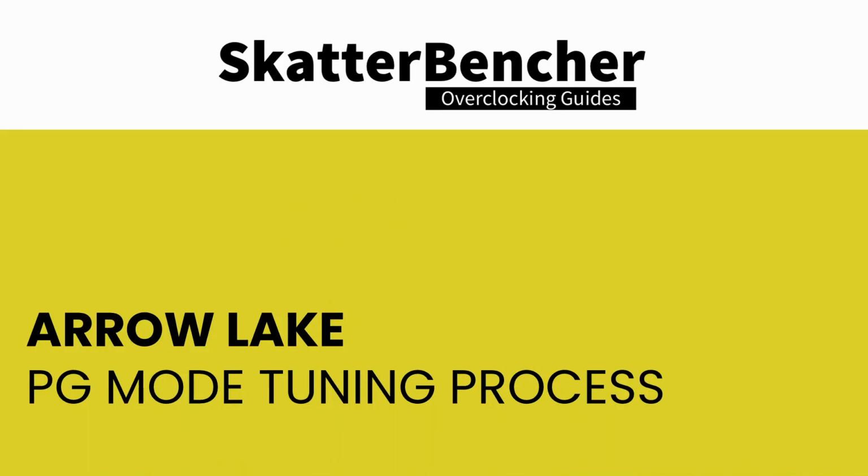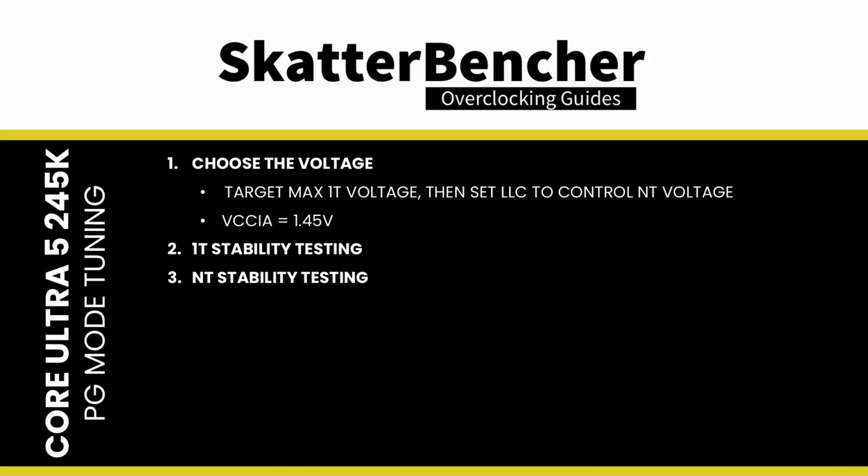The tuning process with power gate mode is actually very similar to how we did it in OC strategy number 2, with one major difference. Instead of relying on the VF curves, we set a static output voltage for the VCC-IA voltage rail and then use an appropriate VR load line to determine the voltage in high load scenarios. The easiest way to choose an appropriate VCC-IA voltage for power gate mode is by first choosing the maximum voltage for 1T workloads, then afterwards configuring the VRM load line to stabilize NT workloads.